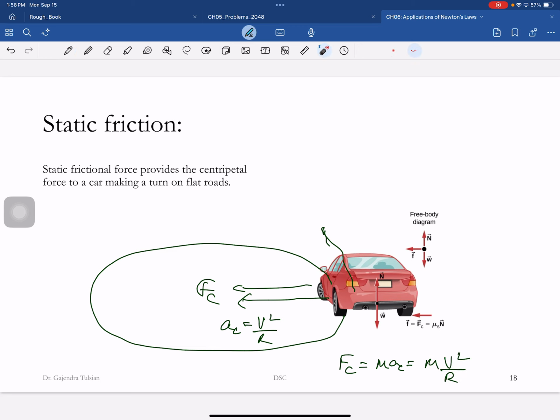So you see that speed limit marked on exits, that speed is such that you don't need any friction forces. Even in the iciest conditions, if you go at exactly that speed marked on the exit, you won't come off the exit, whether you're driving a truck or a car. So this not only saves the nation billions of dollars, but it's also a safety thing.